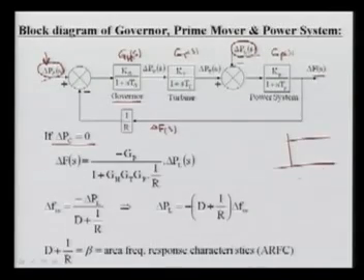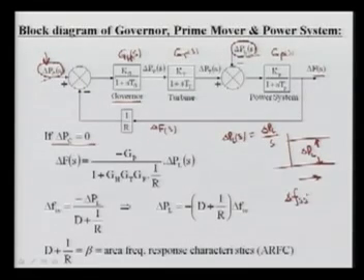If there is a sudden change, a step change in time, let's suppose it changes the PL magnitude. The transfer function of this change in PL in the Laplace domain is nothing but the change in its magnitude divided by S. With this step change in the load, I want to see what the frequency change will be in steady state. This is called the static performance, the static response.